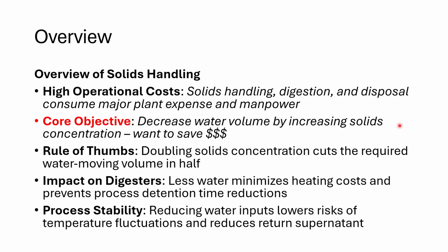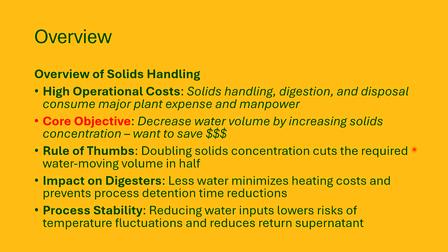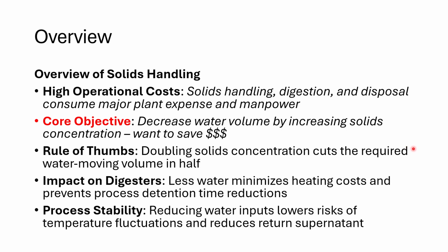We're hauling off very concentrated solids. That's going to save us money over time, okay? A rule of thumb, one item you do want to remember. This is one of those things that'll come up in homework, in a final exam, as well as your certification exam. The rule of thumb in solids handling: when we double solids concentration, we are in effect cutting the required water moving volume in half.